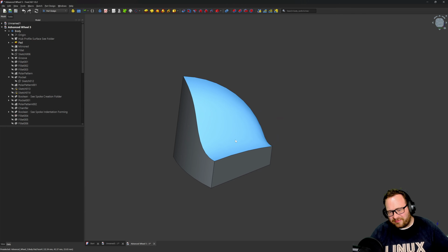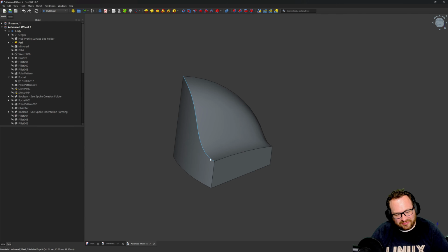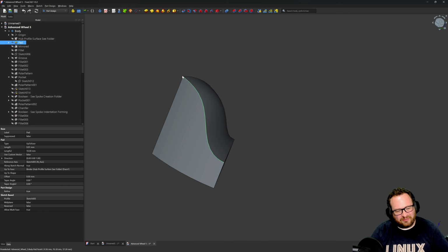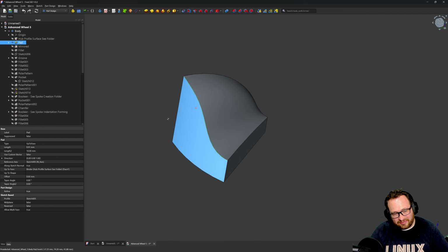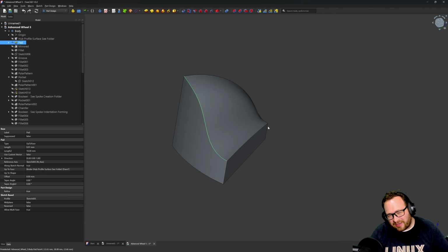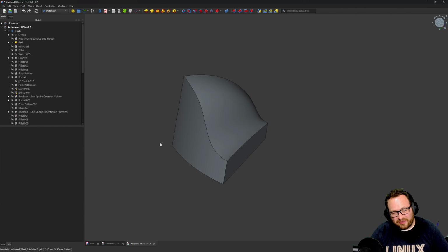So we're going to be using some external features, and our wireframe is going to create that. We need to create something that tells what this outer edge has to be shaped like, right? It looks like a loft that is normal to profile on each side. We really don't have that in Part Design. So how do we do normal to profile lofts? We're going to be using some features from the Curves workbench to assist us.